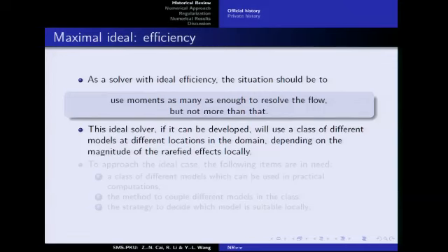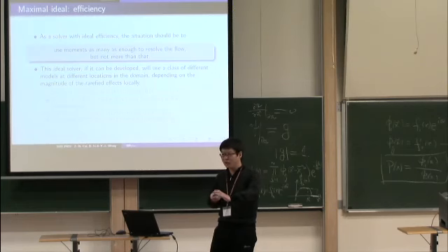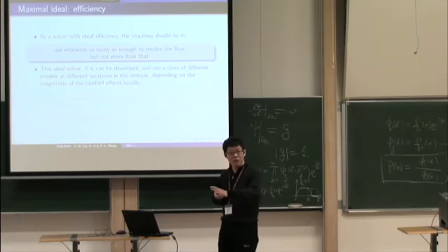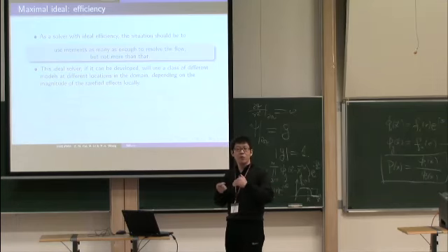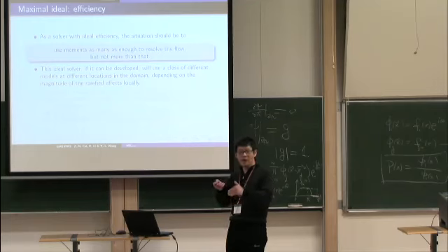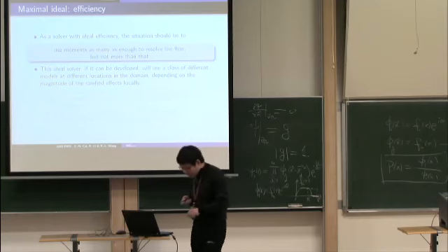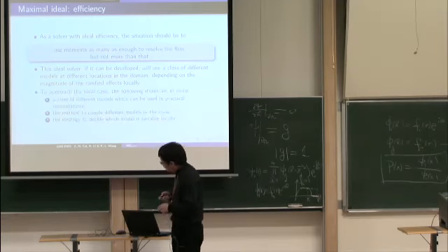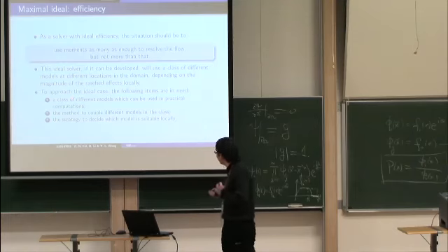The exterior flow field around the airplane, the far field, should be directly simulated using the Euler equations, and in the transition part we will use the Navier-Stokes-Fourier system, and very close to the surface of the aircraft we need to use some system with higher order expansions.